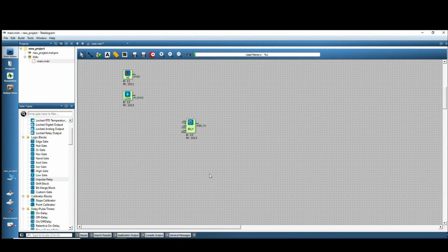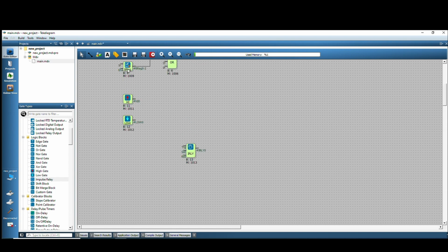When the block output is low, 0, applying a rising edge trigger, logic 1, to the TRG block input causes the block output to transition to high, 1. When the block output is high, 1, applying a rising edge trigger, 1, to the TRG block input causes the block output to transition to low, 0.